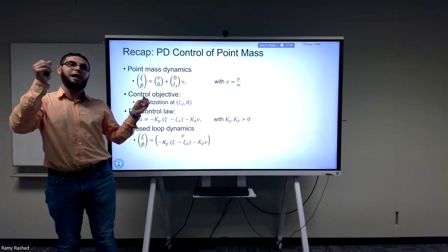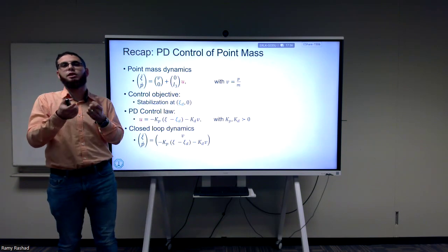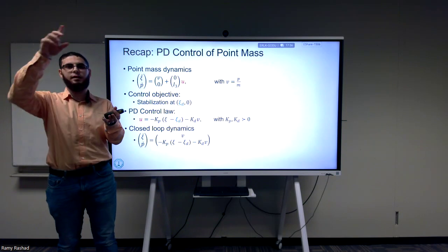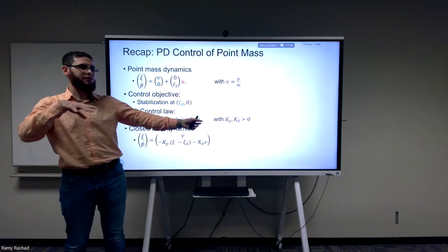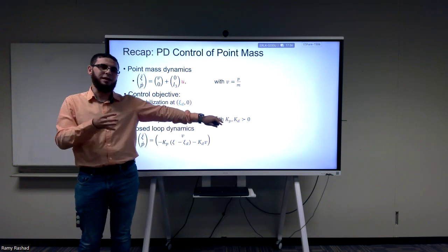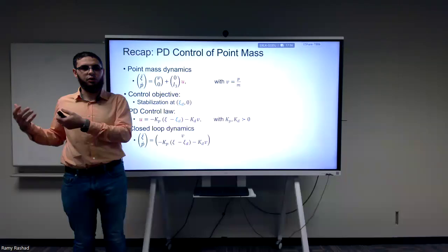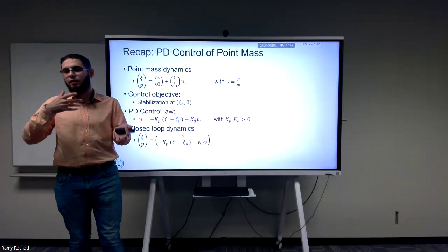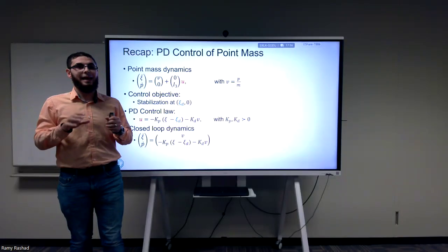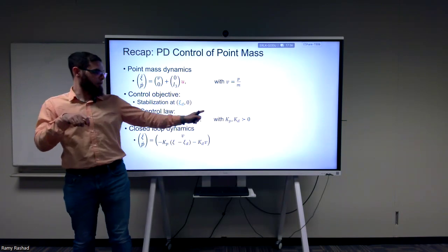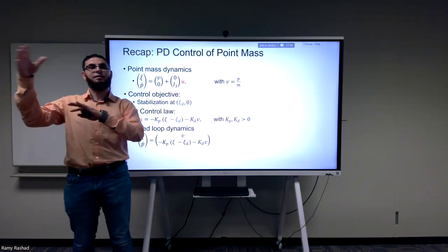We use them as a guide, or as a rule of thumb. So if, for example, you have some overshoot, then you can play around with the D term in the same way, or in the same guidelines that you use for the settling time and the overshoot and so on. But can you write that, for example, the gains here are equivalent to the settling time there?